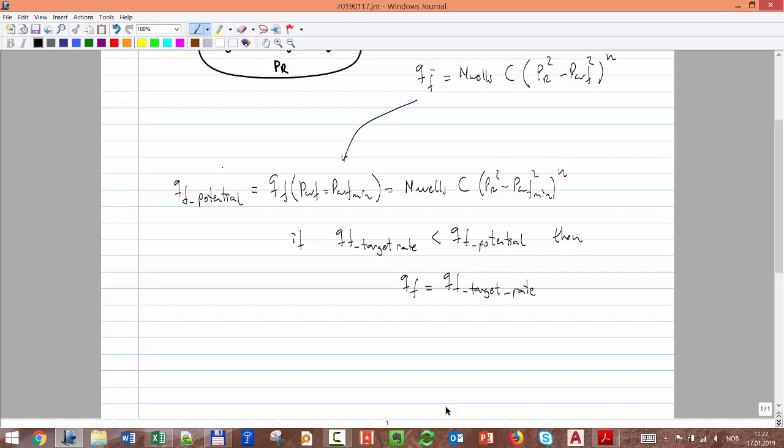And what about pressure? What will be the operating bottom hole pressure? Well, I could use simply this equation, right? But now for the Q, I can simply use Q field target rate, which will be equal to n wells times CPR. But now I just have to clear, I have everything in this equation. I have the plateau rate, I have the number of wells, the C and the N, I have the reservoir pressure, and I simply clear what will be the pressure that I need. Okay, not the minimum, but simply the operating bottom hole pressure.